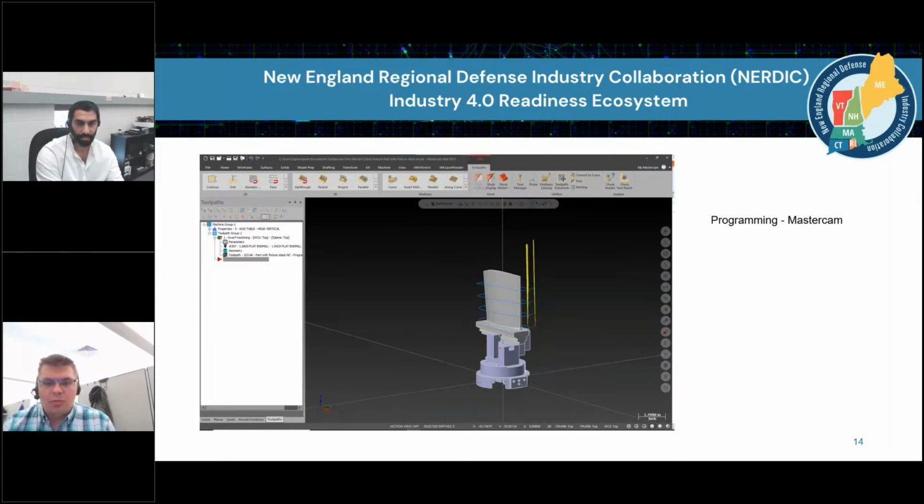So in this case, I'm using a workflow where I program the initial path that the robot takes inside of Mastercam, and basically telling Mastercam that I'm milling with an odd-shaped tool that represents the belt sander as opposed to a round cutting tool. And then that generates the 5-axis path that I'm going to use to drive the robot.